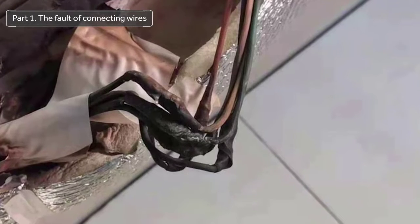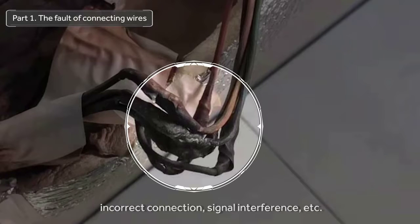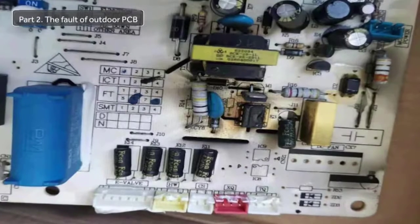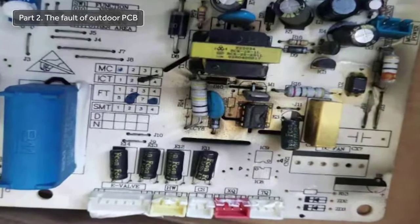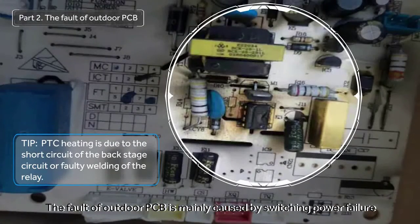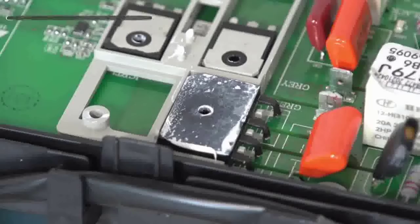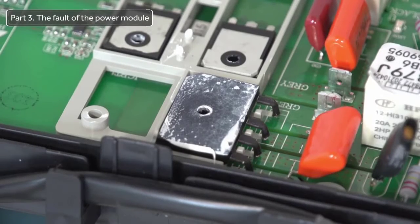Part 1. The fault of connecting wires. For example, wire joints get damp, aging wire joints, incorrect connection, signal interference, etc. Part 2. The fault of outdoor PCB. The fault of outdoor PCB is mainly caused by switching power failure, 16 amp, 25 amp fuse fusing, and PTC heating, etc.